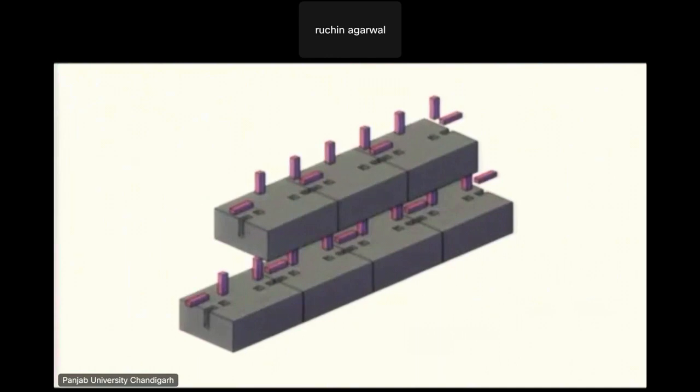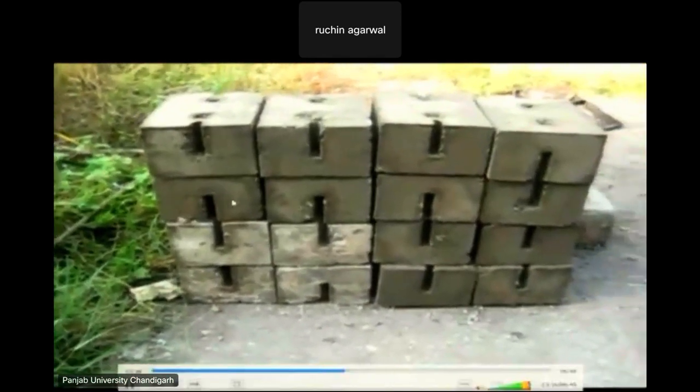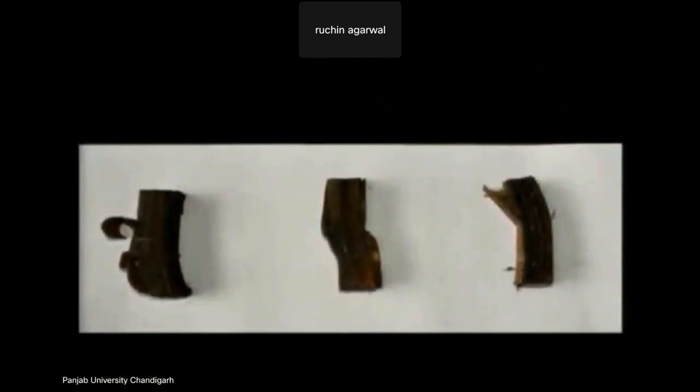Rather, the concrete blocks are provided with 4 vertical grooves to restrict translation and 2 horizontal grooves to restrict rotation under severe earthquake loading. The strength of the concrete blocks is kept much higher than the viscoelastic links for energy dissipation through the yielding of low-strength viscoelastic links and friction between the concrete blocks.